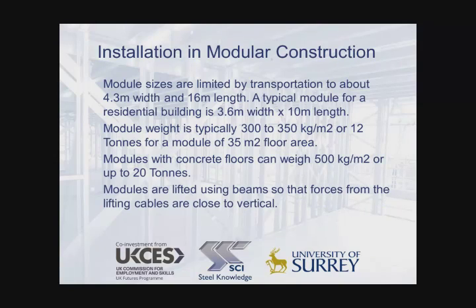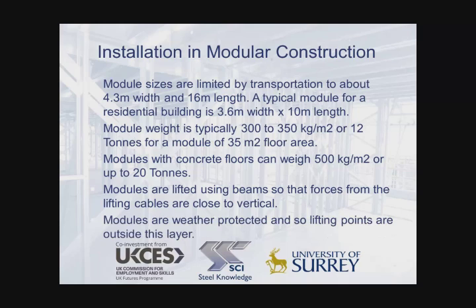Modules are lifted using beams so that the forces from the lifting cables are close to vertical and don't lead to any damage of the modules. Modules are weather protected, and so lifting points are located outside this layer.